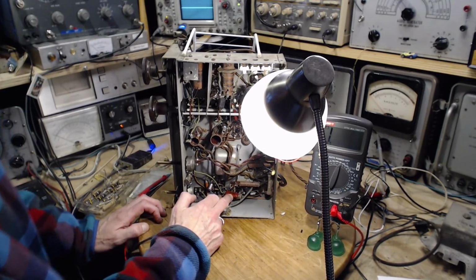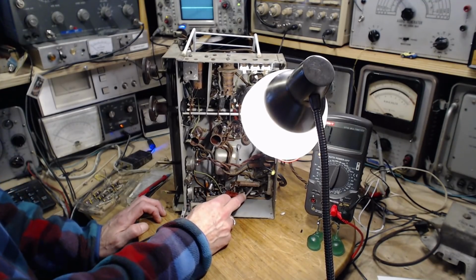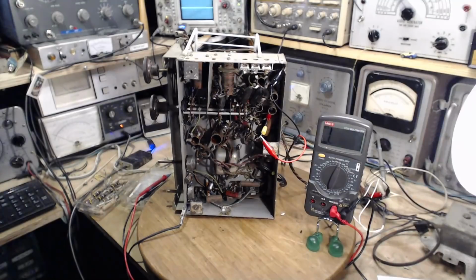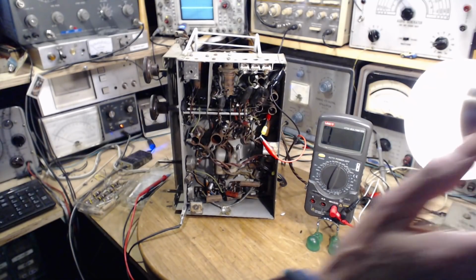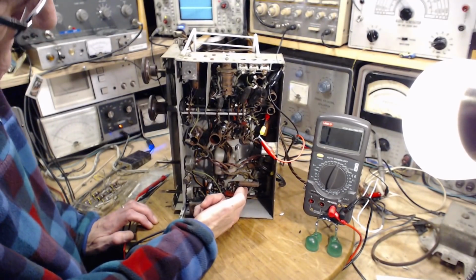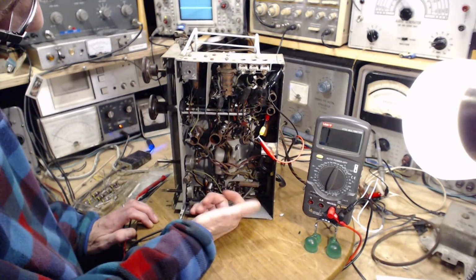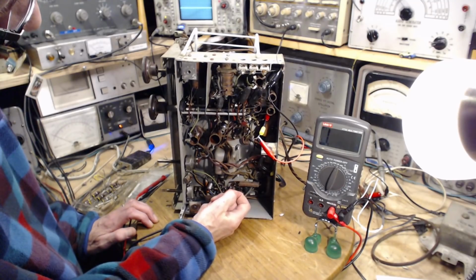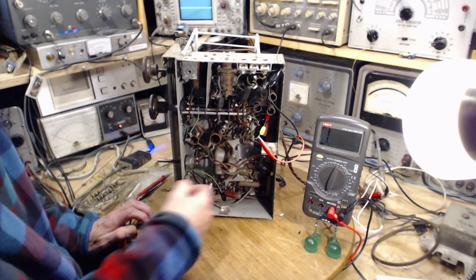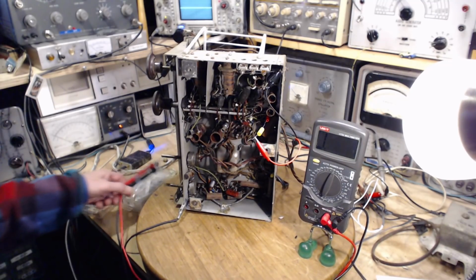You should look on the schematic at the 3 capacitors that are connected to this point and see if any one of them could be a bad actor. Well, the only one that really could be is this black one. It's the only one going to the ground. Tested okay, but the ohmmeter is a lousy test. Let's try it again.